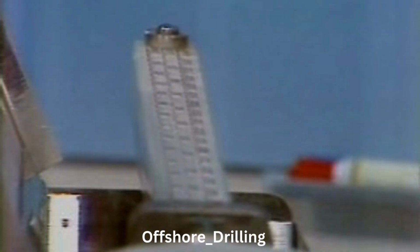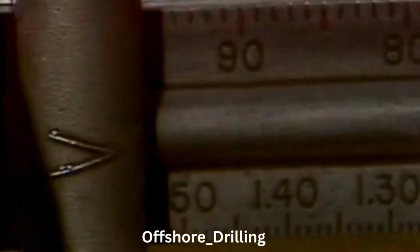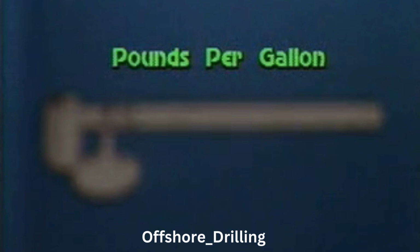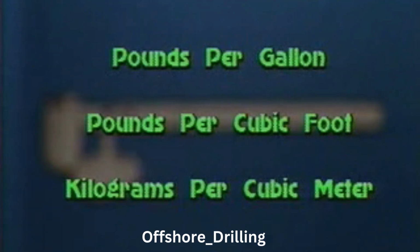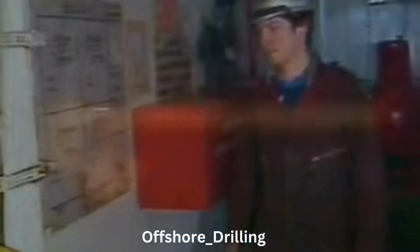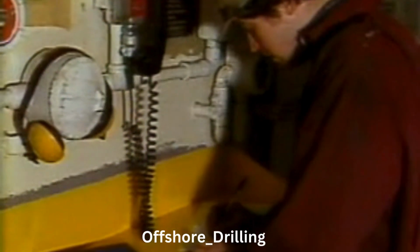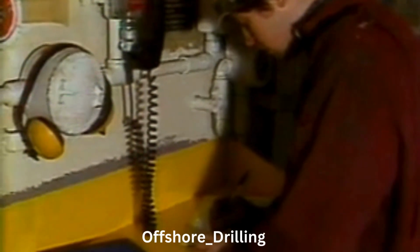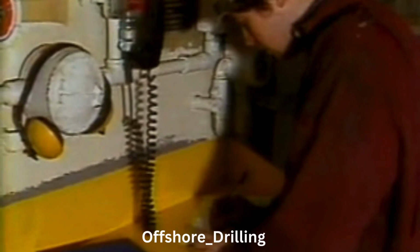There will usually be 3 or 4 scales etched or imprinted into the balance arm. The ones you'll be concerned with are pounds per gallon, pounds per cubic foot, and kilograms per cubic meter. Mud weight should be logged into the mud weight column of your mud logs, along with the time of day that they were taken, and log in the mud temperature too.